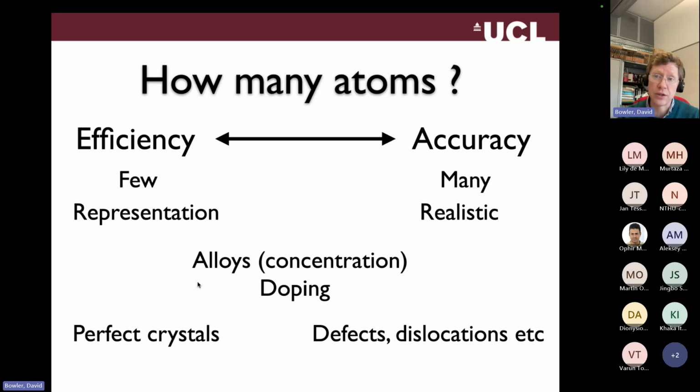We have to introduce electrons to that material in order to allow it to conduct electricity. And a realistic doping level that you would find in a transistor would be somewhere around 1 dopant atom, and we typically use phosphorus as a dopant, to 100,000 silicon atoms. So to correctly model doped silicon in a transistor, we would need at least 100,000 atoms.